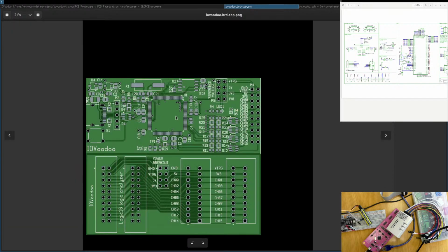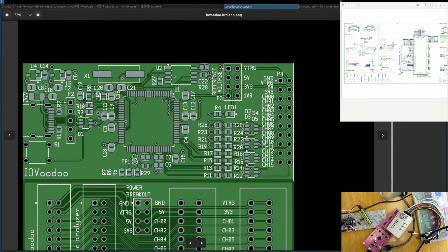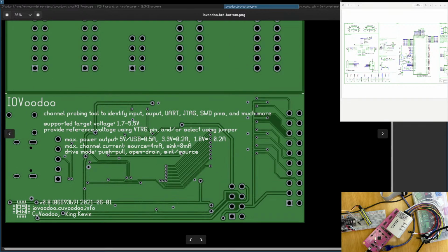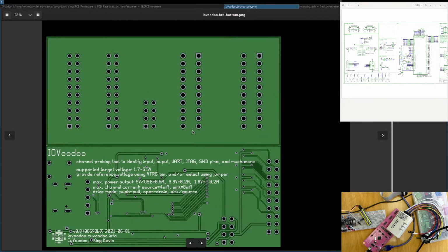I used to have a footprint where this silkscreen line was over all the pads, and the fab house did not remove the silkscreen, which is completely fine because you provide the silkscreen, so you want it this way. If you add silkscreen here, they will add silkscreen in the end. It was my fault. Some fab houses know there should be no silkscreen on the pads. We will remove it, and we will check if the fab house also removes the silkscreen from these things. I hope they do, and they do a negative. We will see.